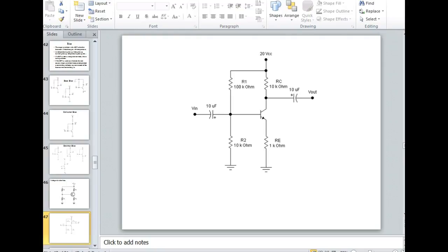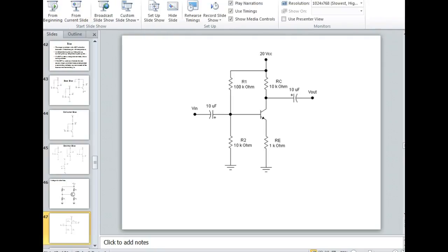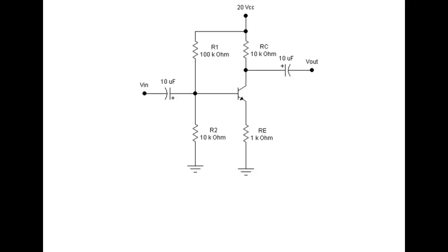DC. And what you do when you start calculating this thing is you picture two individual series circuits. You picture a series parallel circuit, actually. So what you do, if I was to look at this thing, of course, I've done it so long that I can see it in my head. But normally what you do is you come over here and you look at this like this. So you look at this as R1 and R2, and you look at this circuit going to VCC, and you do it. So you calculate that just like a series circuit, right?